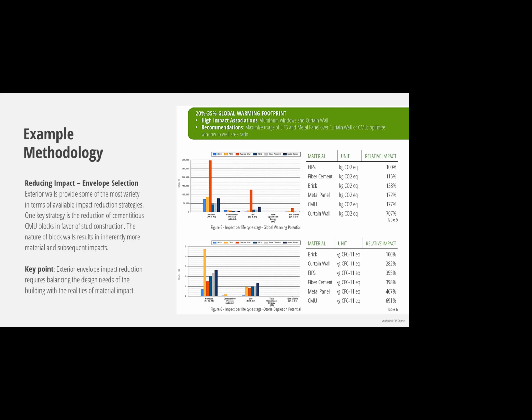So if you look at this chart, we can see that the vertical axis all the way to the left should be the embodied emissions of the material. You can see curtain wall far and away is the highest, but it also has a very high use-phase emission. That comes from the fact that you're going to be replacing glass. It's not always the most durable. It requires a level of turnover in terms of the amount of material, so you're adding material throughout the life of the building. And so that's something to keep in mind.